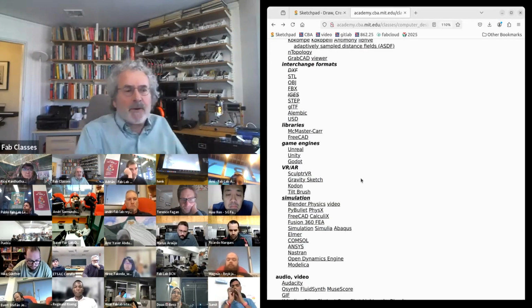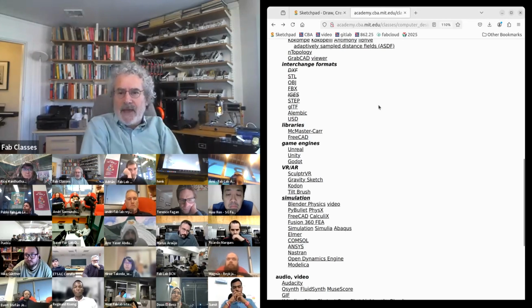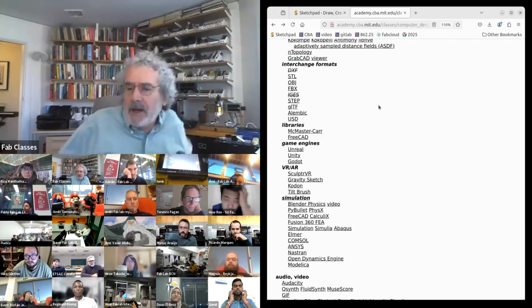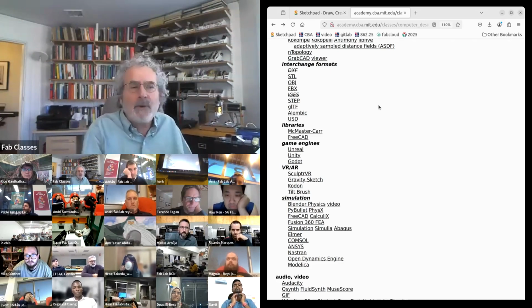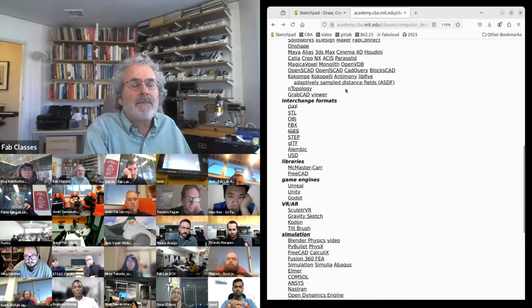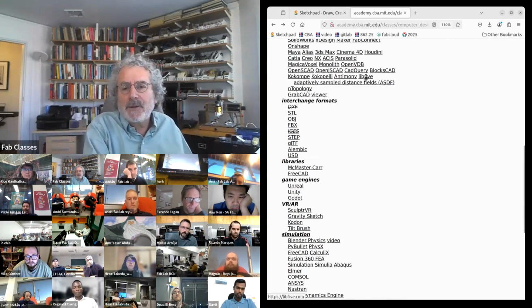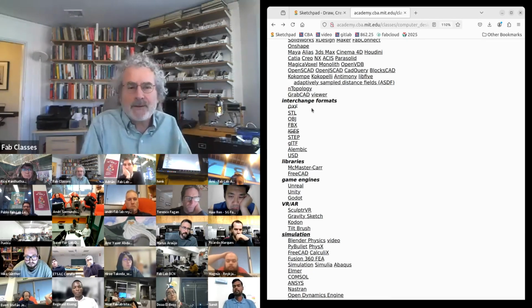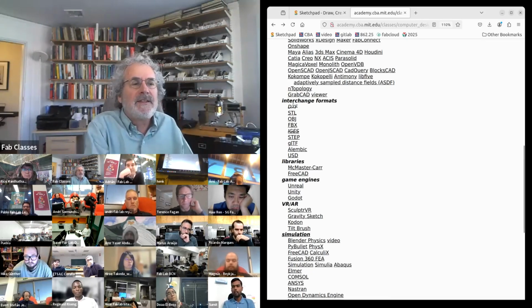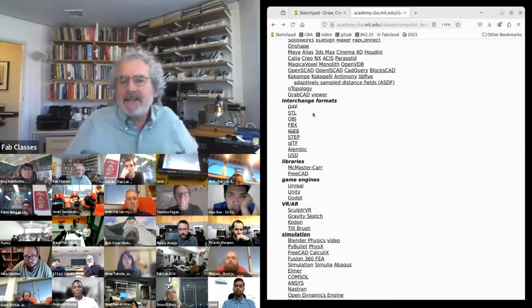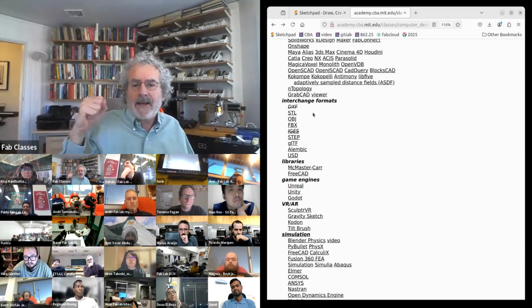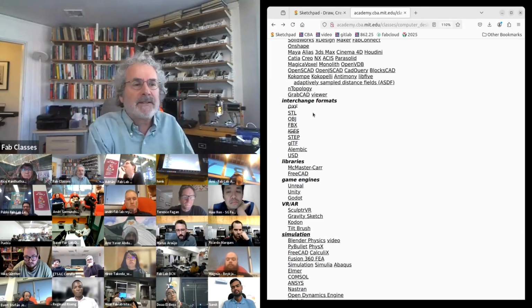Okay, a bunch of things before we finish. So anytime you export from any of these tools into another tool, something goes wrong. Once again, Lib 5 is the current tool that Matt's working on. Anytime you export and import into another tool, something tends to go wrong. Stay away from DXF if you can. DXF is an Autodesk file format. It's not an interchange format. It's a mess. Use it only if there's no alternative.